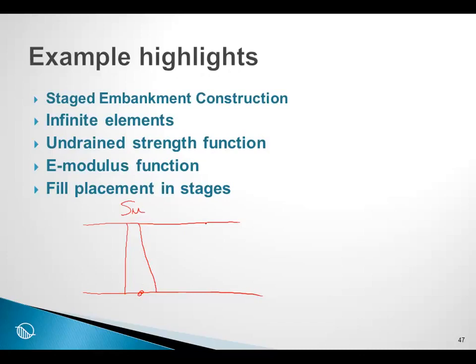The same is true for the stiffness of the soil. At the bottom of the layer, under higher stress levels, the soil tends to be stiffer because it is consolidated to a higher stress level, and so the stiffness, the total Young's modulus, generally tends to increase with depth. We simply say the stiffness increases with depth,